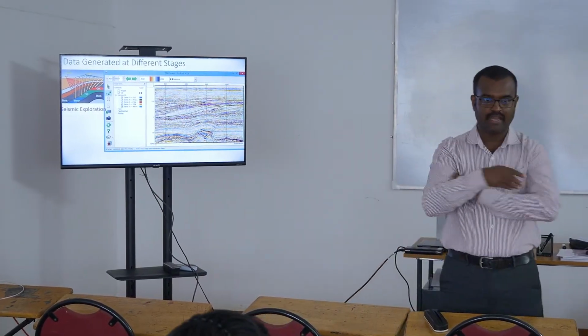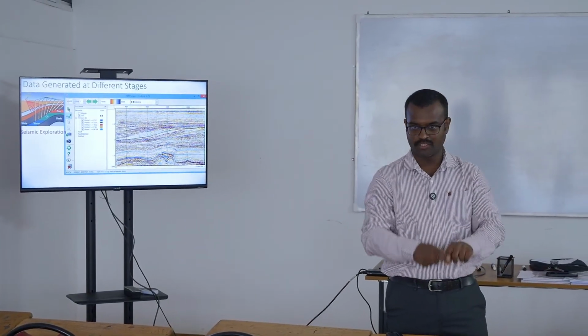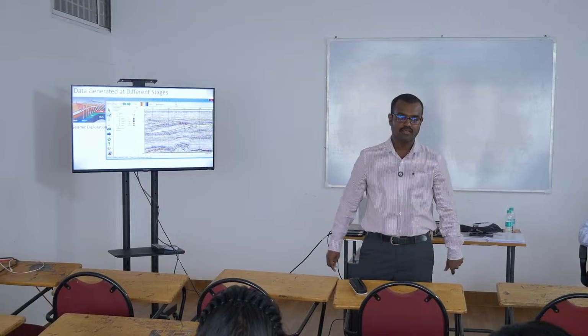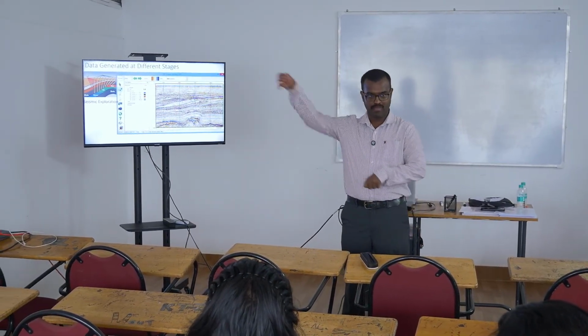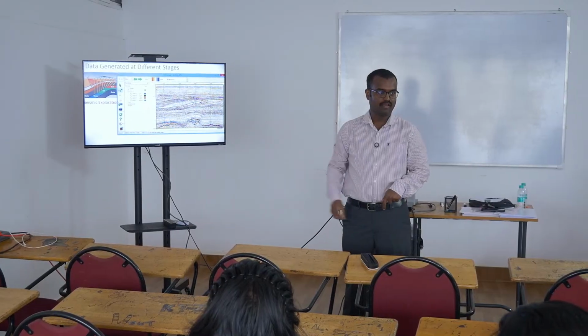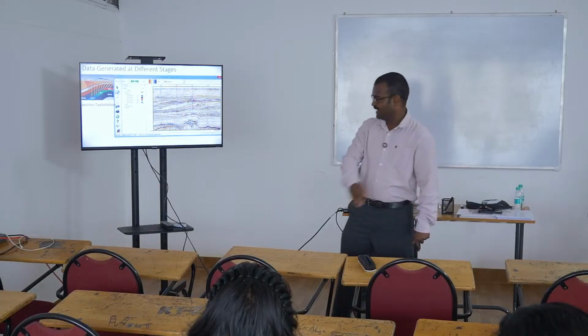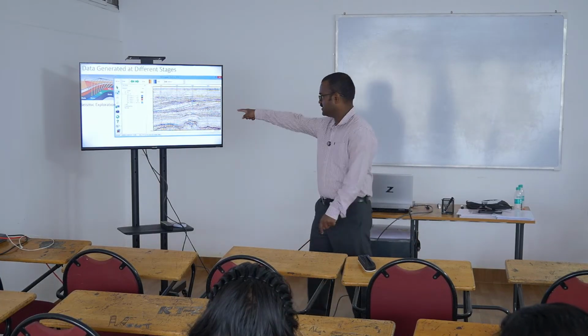So we don't directly go and measure, okay, x comma y, latitude, longitude, this is the depth. You cannot go 3000 meters down and check it. You have to do it inversely. So we pass sound waves and then record back the sound waves. Based on the returned sound waves, we do interpretation. That interpreted image is like this, okay.